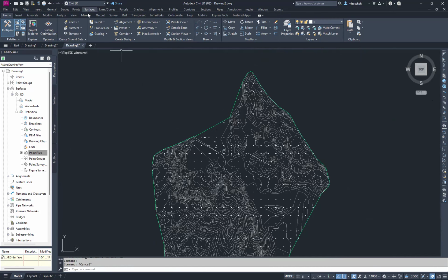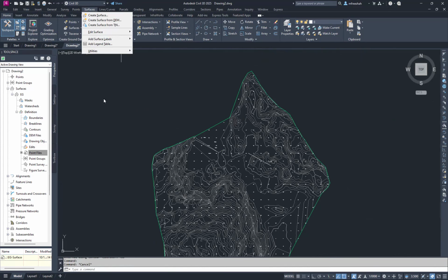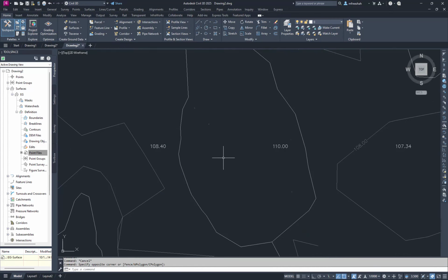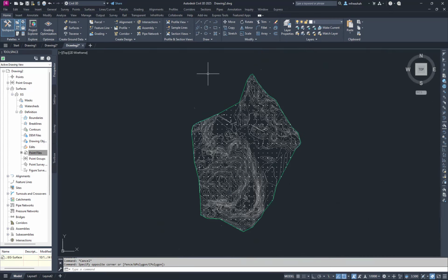That's for label. Now I want to go to calculating cut and volume, cut and fill. For example, here, this is the existing ground surface. I have to compare with another surface, right? To compare the quantities for cut and fill, I should have another surface. For example, I will make another surface with a specific elevation and create the cut and fill between the two surfaces. For example, I make a polyline, PL, or you can choose it from the window here.